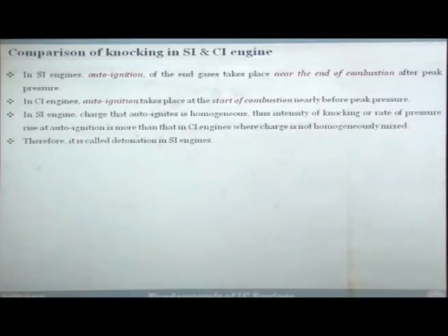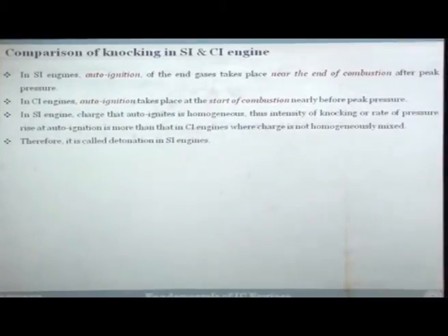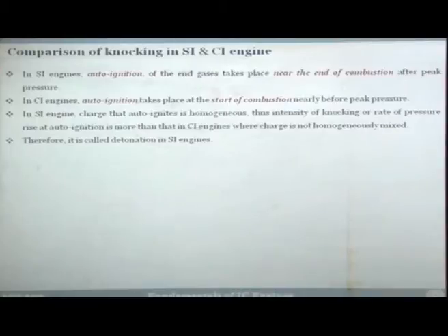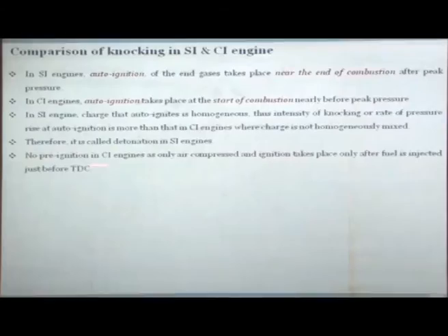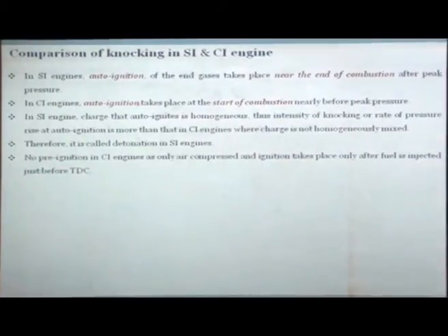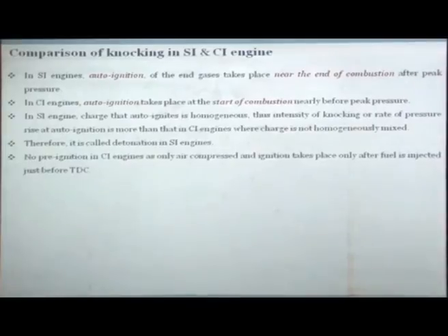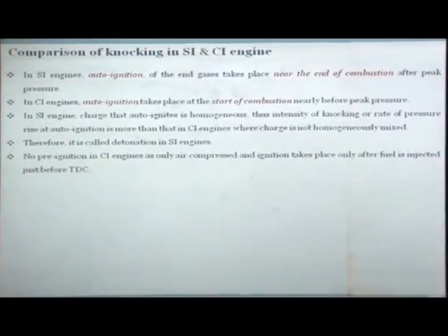Therefore knocking is also called detonation in SI engines. Detonation is a term specific to SI engines. When you say knocking, it can be in both, but if you say detonation, you are referring only to SI engines. No pre-ignition can take place in a CI engine; pre-ignition can only take place in an SI engine, because in a CI engine only air is compressed and ignition takes place only after the fuel is injected, just before TDC. So all the types of abnormal combustion that we experienced in SI engines do not happen in CI engines.